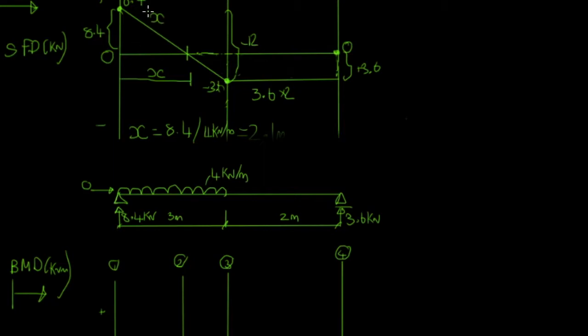And because we've got a linear line on our shear force, we're going to have a parabolic line in bending moment. So the change from this point to point 2 is going to increase. And because at point 2 we know we're going to have a peak because of our 0 shear force, we can expect our line to be like this.